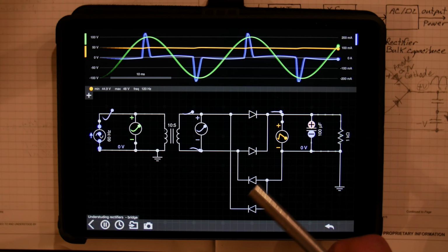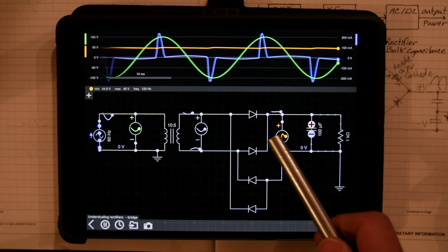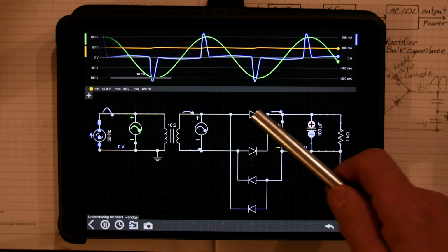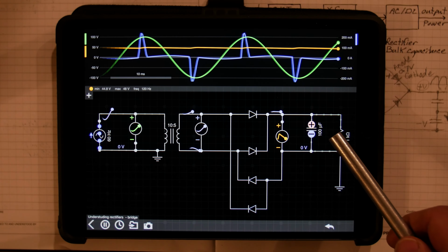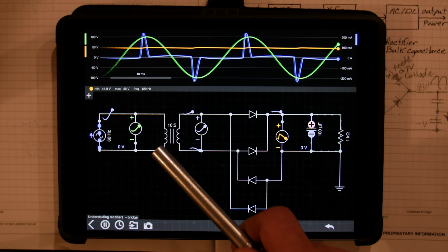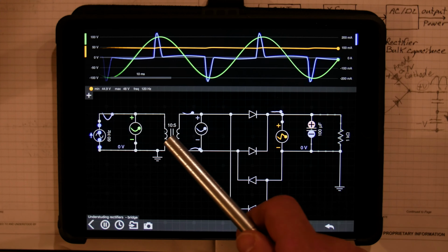So when we select these diodes and we look for these high current things, then you can see why. The other thing is we notice there's voltage drop across the diodes, so that's something for us to consider when we select our transformer. If we want a certain voltage over here, we got to take 2 diode drops into account. The transformer has to handle these high peak currents, so